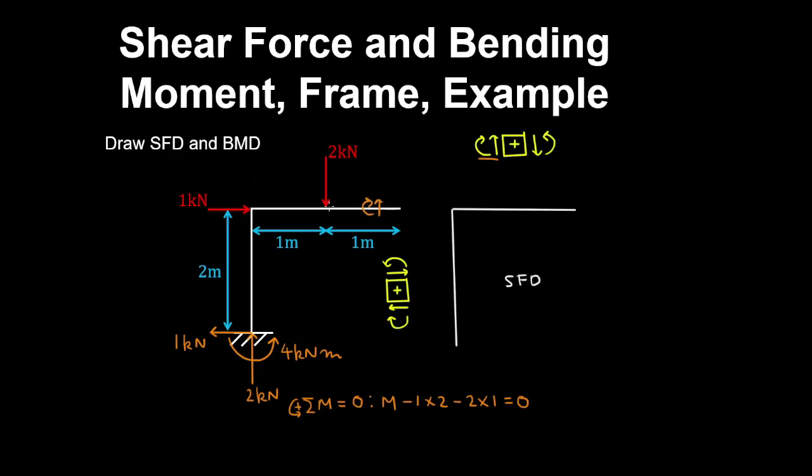And we can see that the shear force is 0 up to the point load. And if we again cut the beam from right to left, we can see that the shear force is constant at 2 kilonewtons by a vertical equilibrium of forces. So that's our shear force diagram, constant at 2 kilonewtons for the beam.